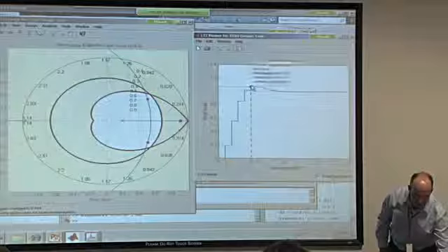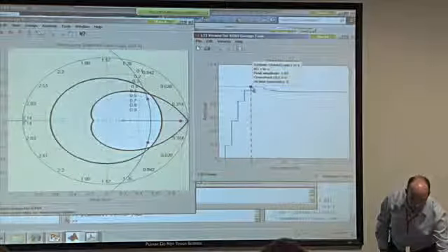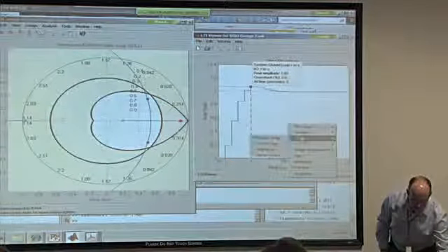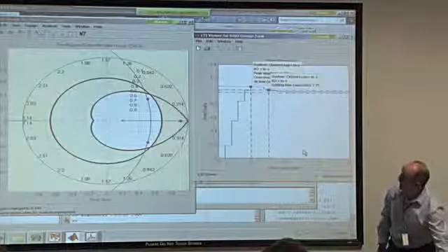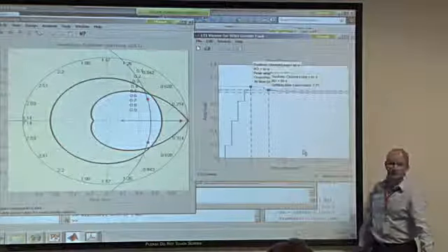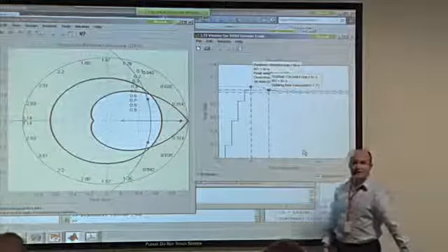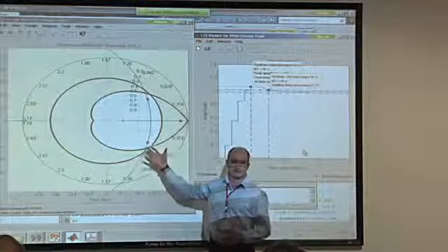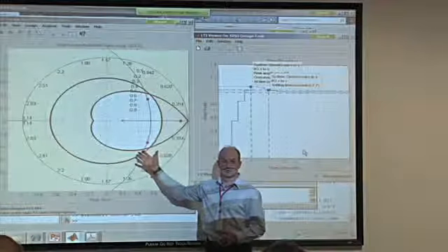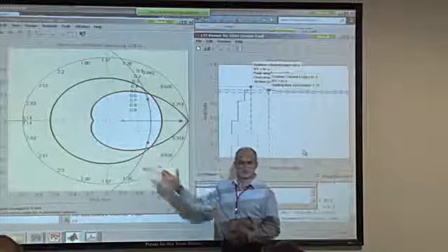Peak response is only 6.8%, and then the settling time 7.71 seconds. It's rather good, isn't it? So it's just a matter of proceeding exactly as we did for the continuous time system, but making allowance for the fact that it's the Z-plane we're working in, not the S-plane. See how that works?